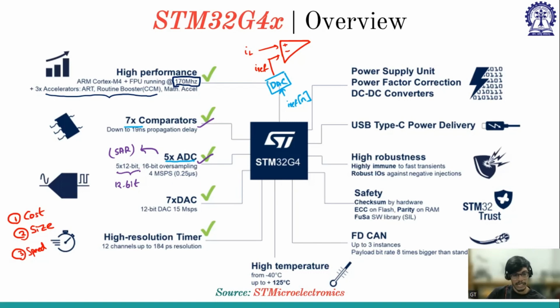When I design, say, for a buck converter, say I have designed a voltage mode controller, based on small signal analysis I have a requirement on bandwidth and a requirement on phase margin. Either of these can be achieved using FPGA or microcontroller, but it is up to you which one you want to select. And you have to look in depth.